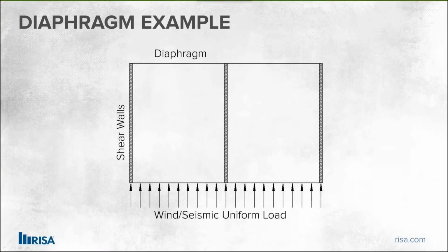So looking at this in a plan view, we're looking down on this model now. We're thinking about these as shear walls. We'll simplify this to a simple 3-wall example: shear walls on the outer edges and in the middle, and the diaphragm is just going around the edge there. So assuming it's a typical floor model, we're just looking at one floor level.